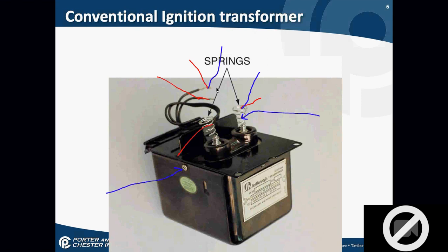Honestly, if I get good wire and my transformer's good, I'm checking my entire ignition. Checking the entire nozzle assembly next. Or I've already checked my nozzle assembly, depending on what I'm there for. Because the ignition transformer directly feeds the nozzle assembly.